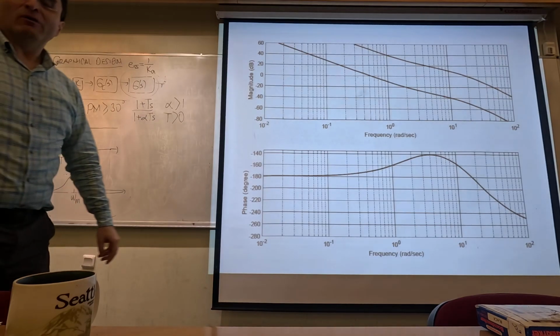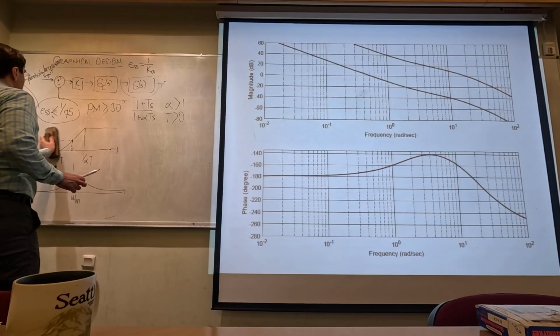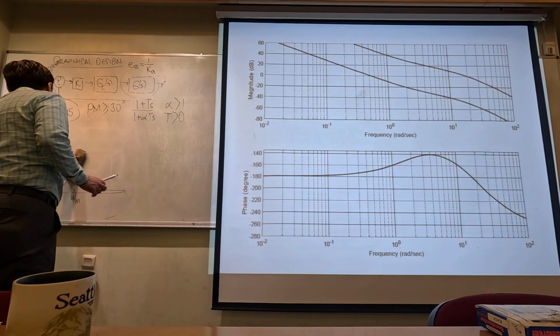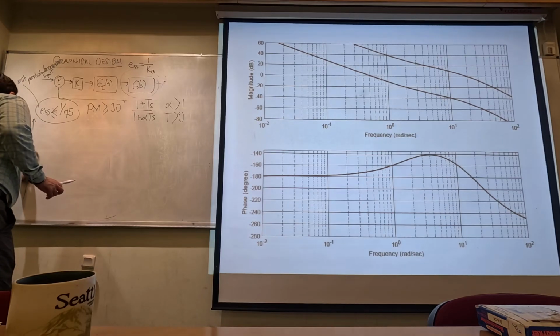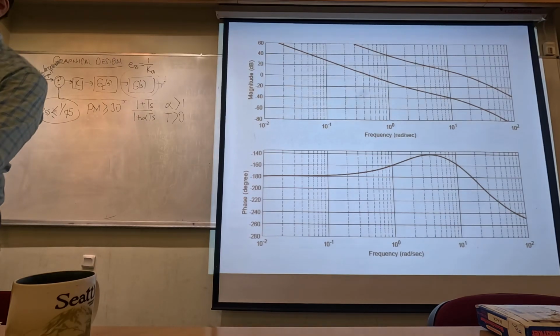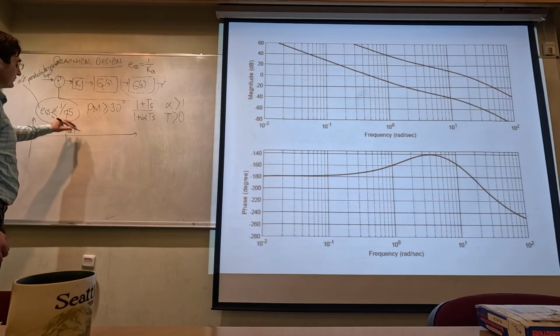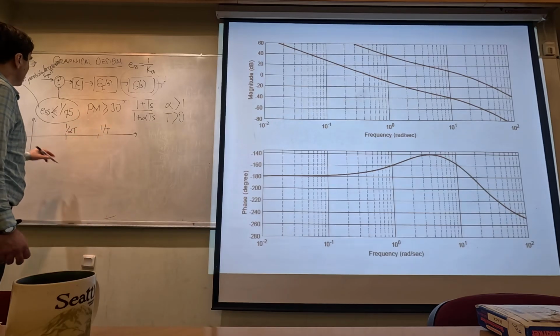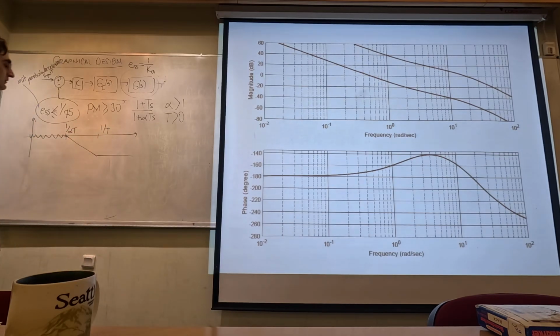Now let us look at the phase lag compensator, where we are going to use the gain only to achieve our performance requirements. When I concentrate on the phase lag compensator, the magnitude is going to be just the reverse of the earlier case. This is 1 over alpha T, 1 over T now. When I look at the magnitude, I will get this thing.